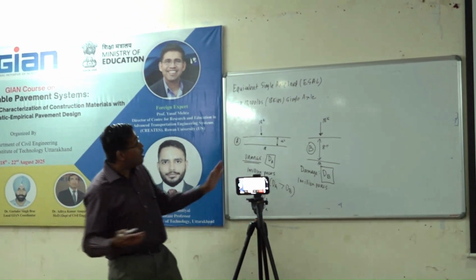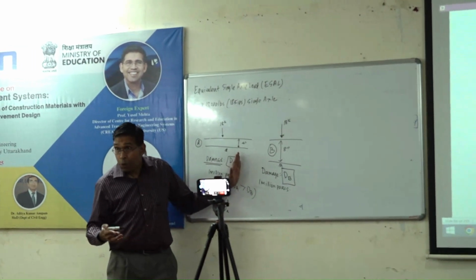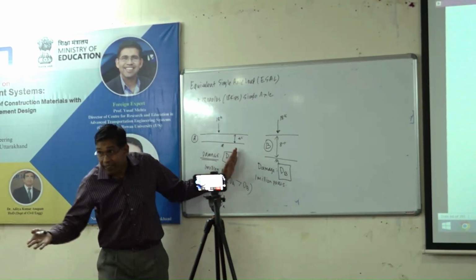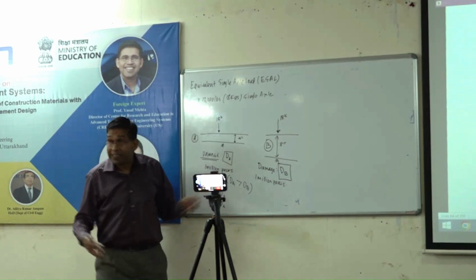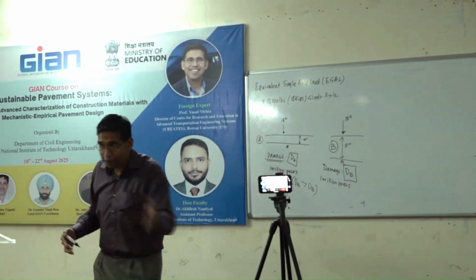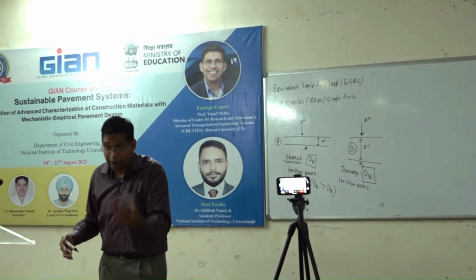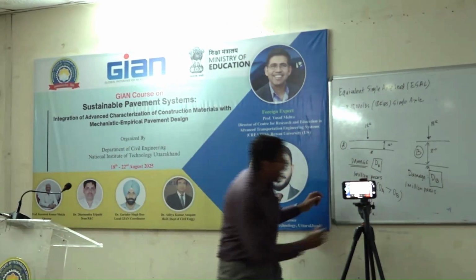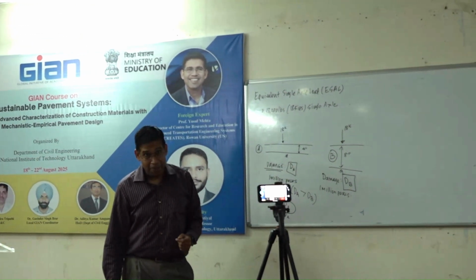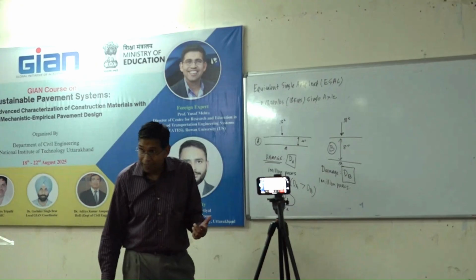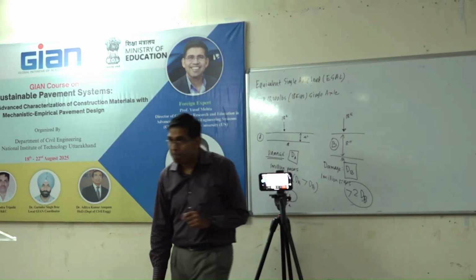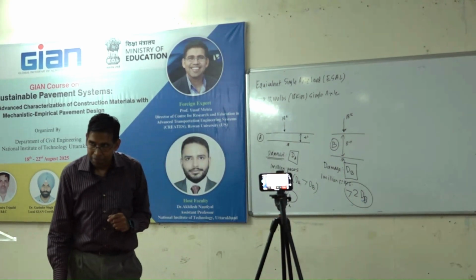So, the moment you have applied a certain amount of damage, it's like human behavior: you don't have the same structural integrity anymore. That same million passes will seem a lot heavier. The same exercise you do in the morning, after a full day of work, will seem a lot heavier. Does that make sense? Therefore, yes, the damage will be greater than twice dA, because you have broken down that pavement. Same thing here: this will be greater than 2 dB because of the same thing. Everybody with me so far?